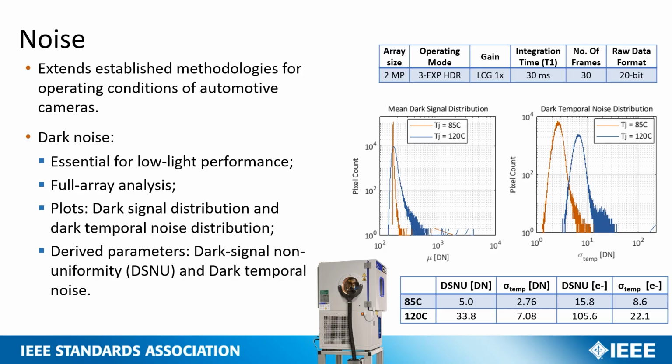So what the standard defines are many different metrics for the dark noise. As the dark statistics are quite important for designing and for checking your sensor, there are different metrics that are defined for that. What is interesting is that it is important to perform dark signal measurements over different temperatures. That's where, for example, our IQ climate chamber is of interest, because it's a setup where you can easily change the intensities or the temperatures and then measure the performance of the imager over temperature.